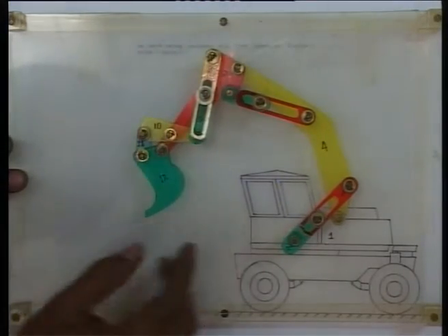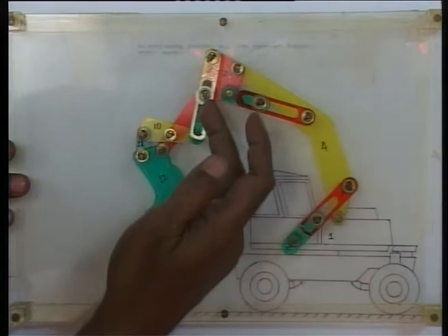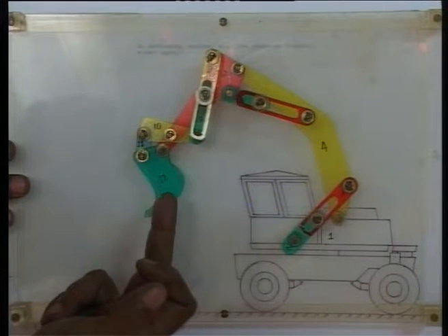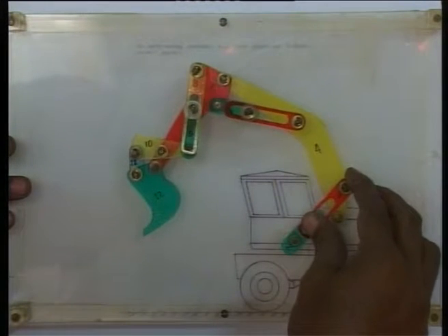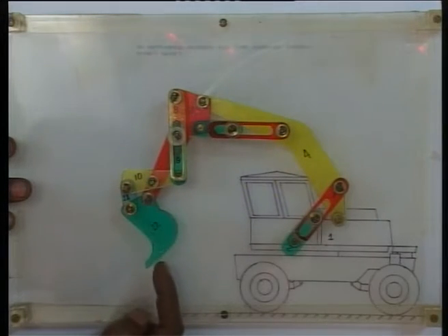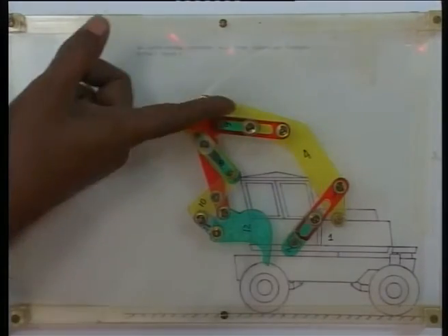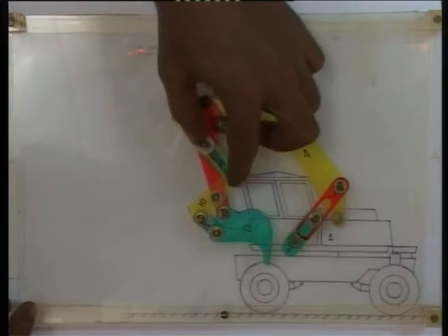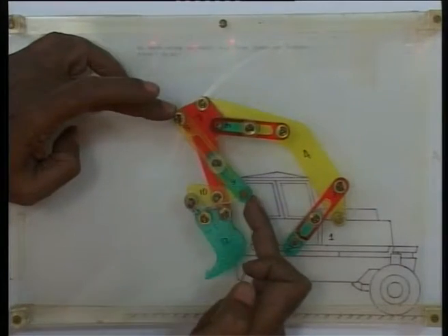the output bin can be moved in this plane of motion. In fact, there are 3 independent inputs. So, all the 3 motions, that is 2 translations and the rotation of this output bin, can be independently controlled. As we might notice, if this hydraulic cylinder is moved, not much change in the orientation of the bin is taking place. Same is true even for this actuator, whereas the third actuator is mainly changing the orientation of the bin without causing much change in its location.